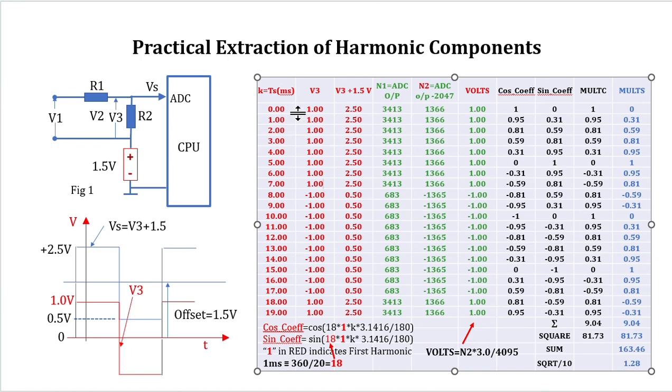All this had to be done because this was not acceptable to the microcontroller. So we had to do these steps, 1, 2, 3, and 4, converting this into this. And once you have this, then our real mathematical jugglery will start. Here you have cos coefficients and sine coefficients. You have seen in the previous page that these coefficients you do require. So you tabulate them. So you have 2 arrays, this one in your firmware and this also in your firmware. You need to create arrays.